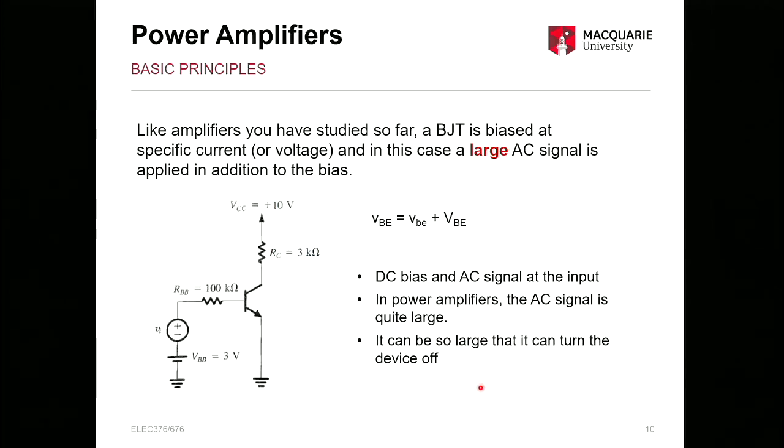Now, as I said, it can be quite large. It can be large enough to actually switch the transistor off. So you need to carefully design it with some knowledge of what kind of input and output signals you're going to have, so that it stays within the correct regions of operation.